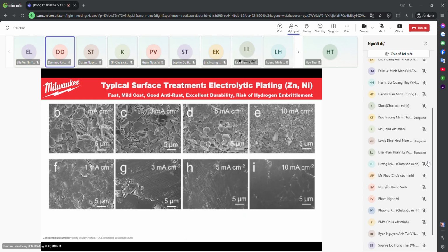And again, after the plating, we can see the surface layer. So anyway, it tells us that with the fine-tuning of the electrolytic plating processes, like the electricity and like the voltage, we can get a good, uniform and consistent coating layer. And that gives us a very reliable performance under the neutral salt spray testing.